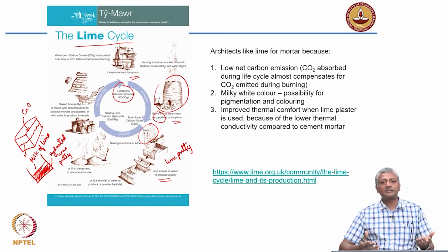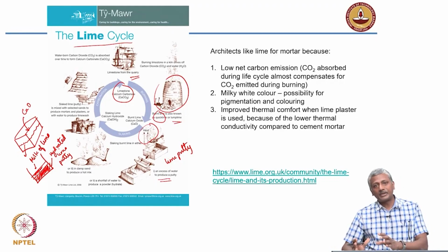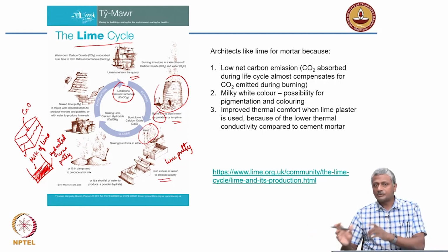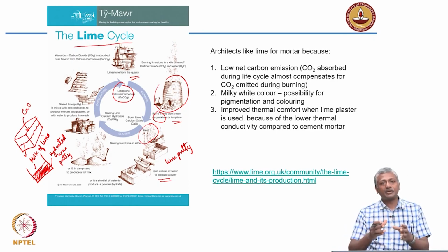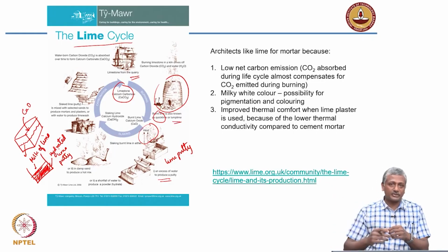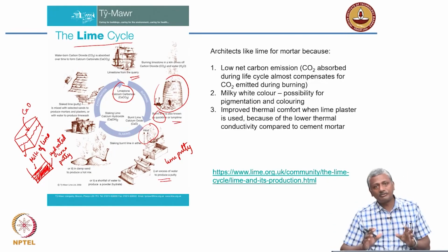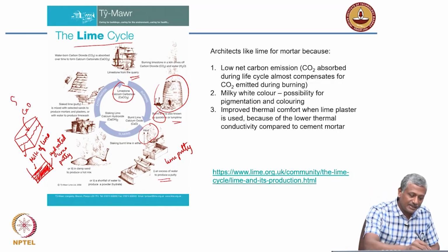The process of slaking simply is done so that all the lime gets converted to hydrated lime before the use in mortar. This is very important because the process of slaking ensures that you won't have any remnant calcium oxide left out, which will convert to calcium hydroxide later in the structure. So that is very dangerous. You want all of it to get converted to hydrated lime in the slaking tank itself. So that is called a slaking tank.